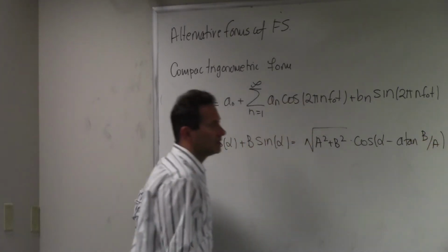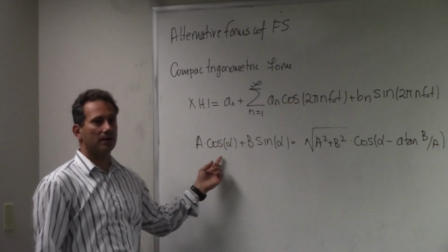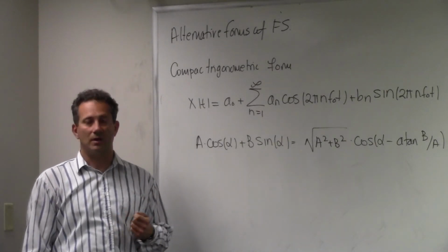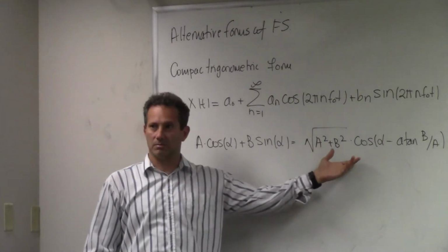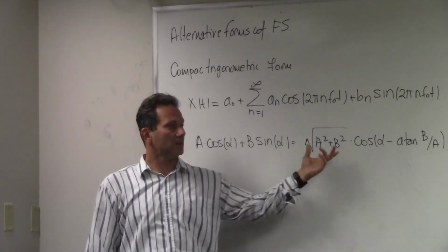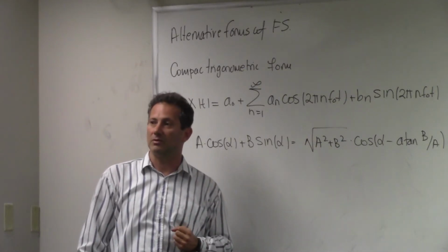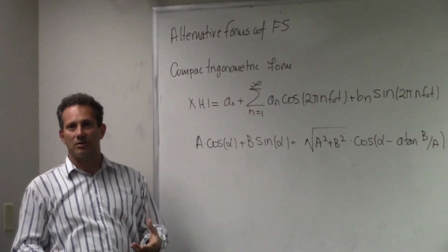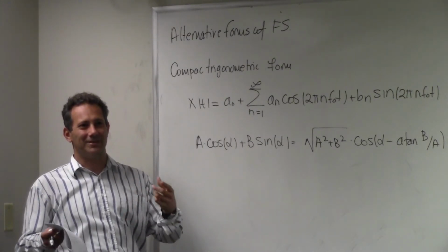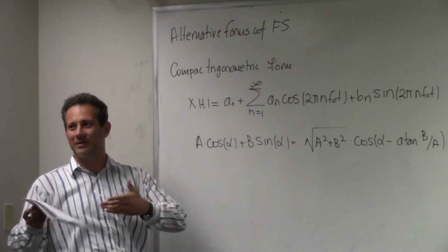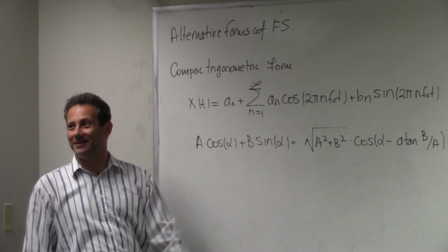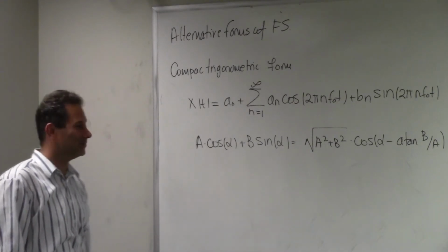Which tells us that if I have a sine and cosine of the same frequency, and I add the two, I'm going to have the component, which is the cosine of the same frequency, just shifted in phase and possibly modified in the magnitude. In other words, when you add sine and cosine, there is no sine and cosine per se. It's just this one cosine that's shifted, based on a, and then it became sine, right? By shifting by pi over two.